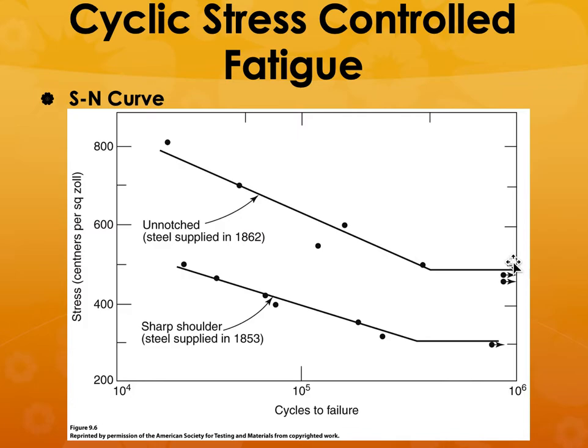Now if you have FCC and very plastic type of materials, this hockey stick will not be a very sharp change in the failure mode, but what you will see is a gradual increase in the number of cycles to failure as a function of stress.